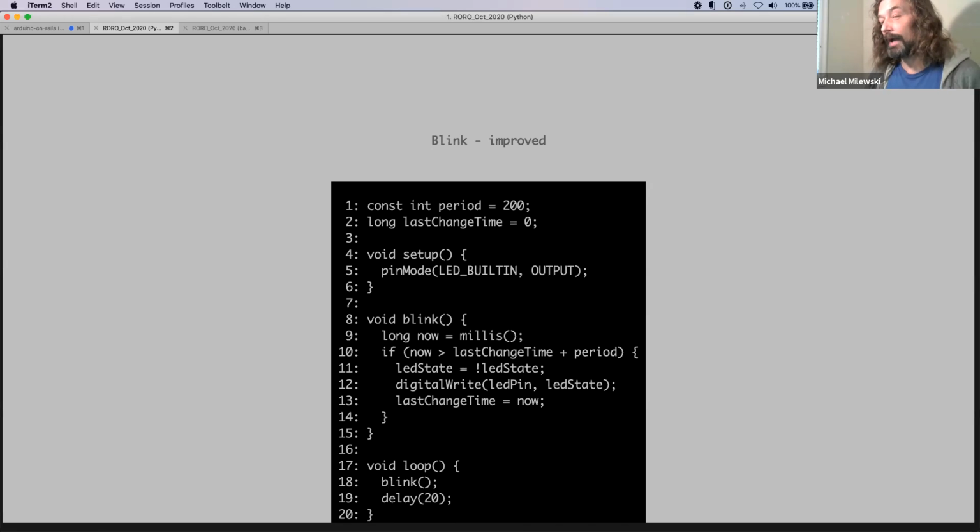And in there, I'm actually calculating based on the last time I've turned this on and off using millis, which is on line 9, which is basically the number of clock cycles since I've turned the Arduino on. So it starts at 0 and just keeps going until it runs out of however big a long is. But obviously you can see, just for my program to start to think of being interrupted by other things, I have to do quite a lot of different coding just to do that.